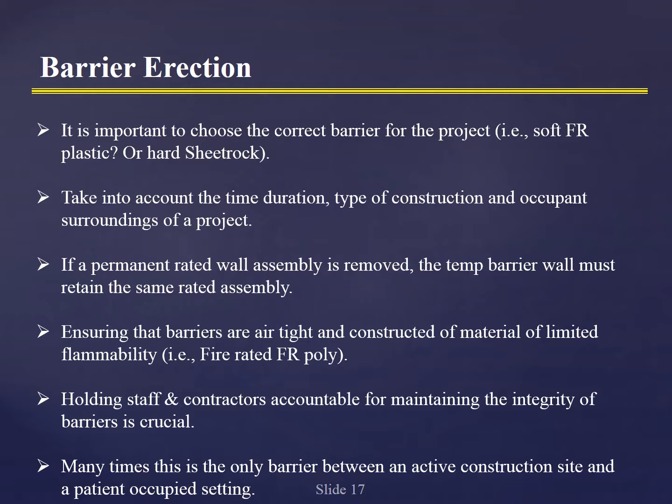And so you could see a very significant potential for contamination to be coming down above the patients through holes where lights were, or through a sprinkler head if there was an escutcheon plate missing, or if a tile was broken or whatever. It could be a very serious way for that construction dirt and dust and air to be pushed through above the ceiling. So again, you really have to understand that there's a very thin margin of protection for the patient sometimes during construction.